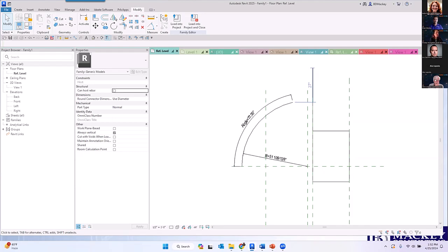Another question came in while you were covering that one. I know currently there is no way to downgrade a Revit family to previous versions. They're saying from 24 to 22. What would be the best workaround? There's a lot of workarounds. Unfortunately, you're going to lose any constraints you have associated to that. So if it's a parametric family, it's gone.